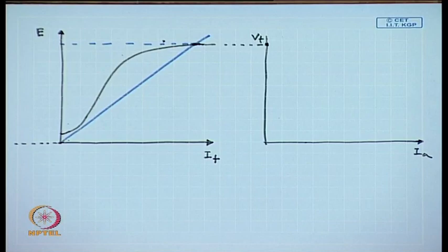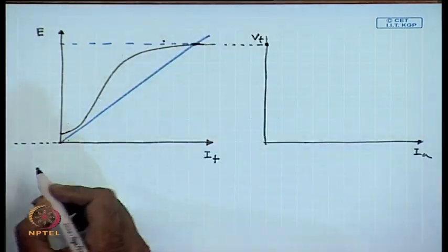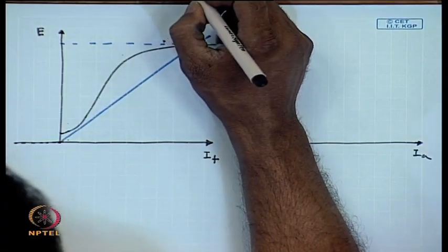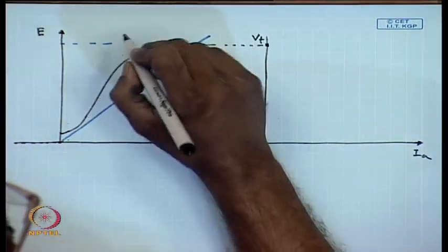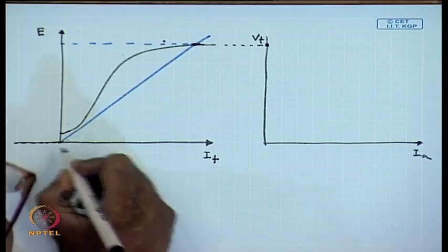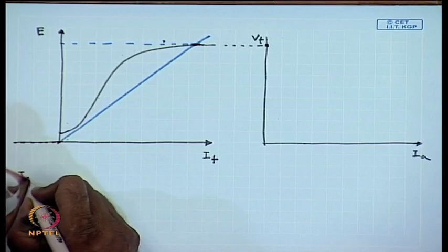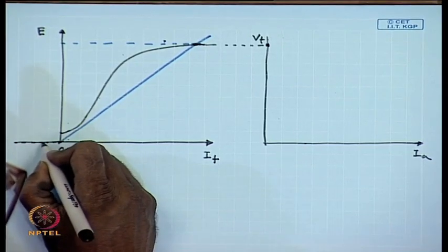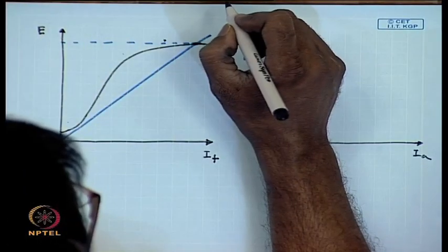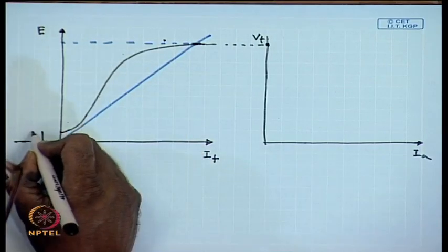At any other load current, at any other armature current IA, we know that the armature reaction corresponds to a negative equivalent field amperes. Let us say at any given armature current IA, the corresponding equivalent armature reaction is OB, and the armature resistance drop is given by BC.